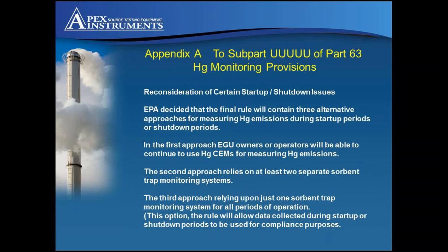So, like I say, mentioning this section, Appendix A to Subpart UUUUU, I'm actually going to just refer to this document as Appendix A. This is where your monitoring program and equipment requirements may well become a little bit more onerous. We've already spent some time looking at all of the QA specific items that have to be achieved to conform to PS12B. And we're pretty comfortable that our sorbent trap monitoring systems will meet those requirements fairly easily, with a high degree of automated data collection, data recording during each sample run.